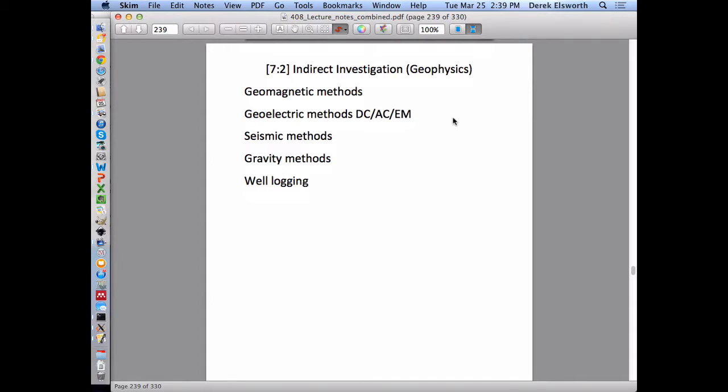And so if you don't put instrumentation in these, then oftentimes you'll backfill the hole with grout just so there's no communication. And I think even with the geoprobe methods, when you withdraw those, often they'll be backfilled along the path of this probe just by squeezing out grout so that you don't end up with, again, this small hole that will collapse that will allow aquifers to communicate.